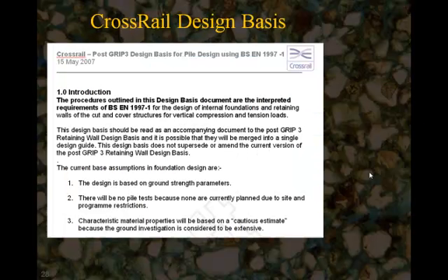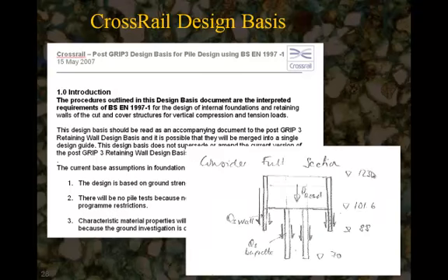These water-related issues have been important on a number of designs. For example, in the Crossrail design basis, they considered the use of Eurocode 7, and it turned out to be particularly important to the design of some of the deep basements there, deep station boxes, where the question is, how do you hold the box down against water pressure?